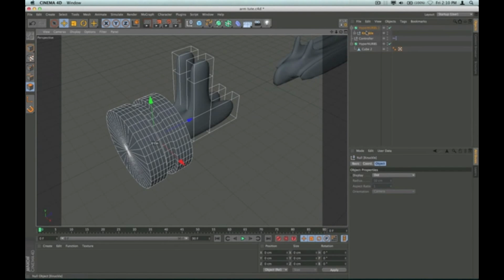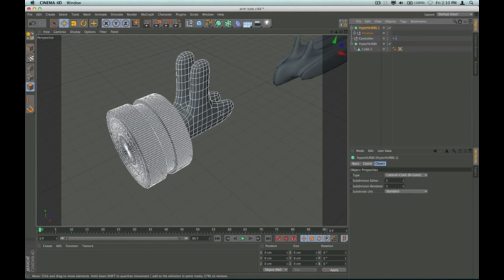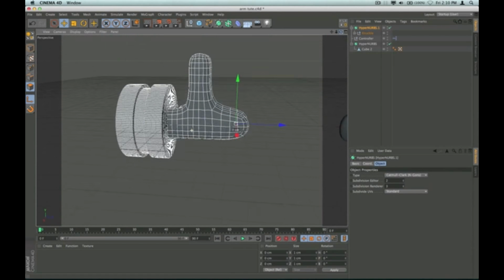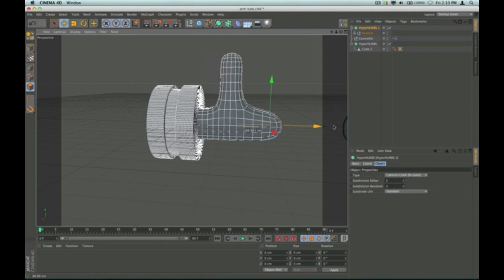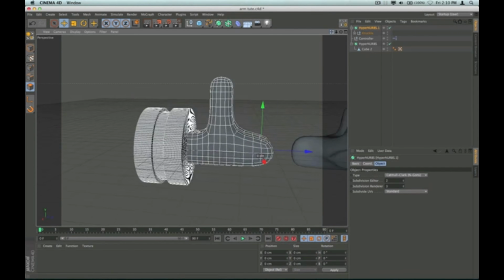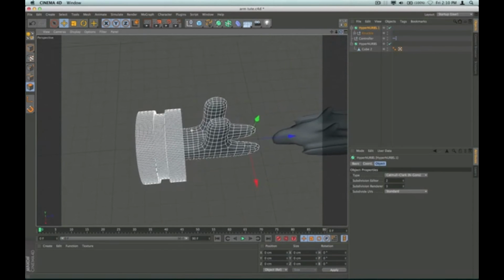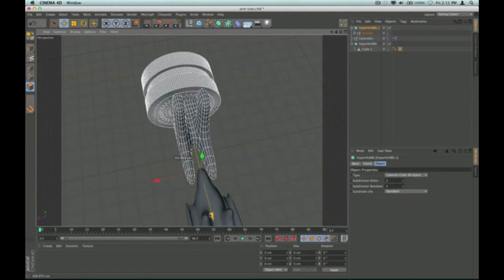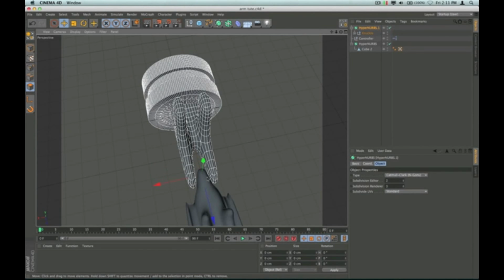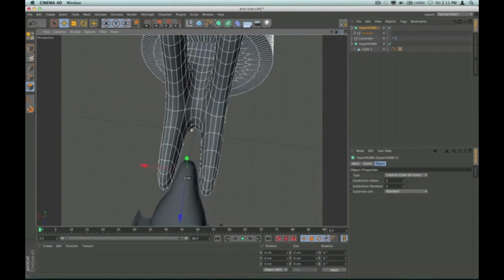Okay. Now I need my hyperNURBS anchor point to be right here. So I'm going to use my anchor point move tool and slide that down. Roughly that position, maybe a little more out. And then click off of my anchor point movement tool to slide the Knuckle into position. And I want to look at it from the top to see where they're lining up. I want them overlapping a little bit but not intersecting. That looks pretty good.